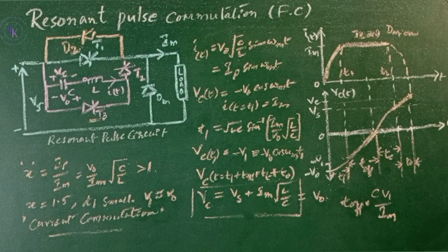Once the current of the thyristor T1 is reduced to 0, the reverse voltage across T1 is the forward voltage drop of diode D2, which is small. This will make the thyristor recovery process slow, and it would be necessary to provide a longer reverse bias time than if the diode D2 were not present.